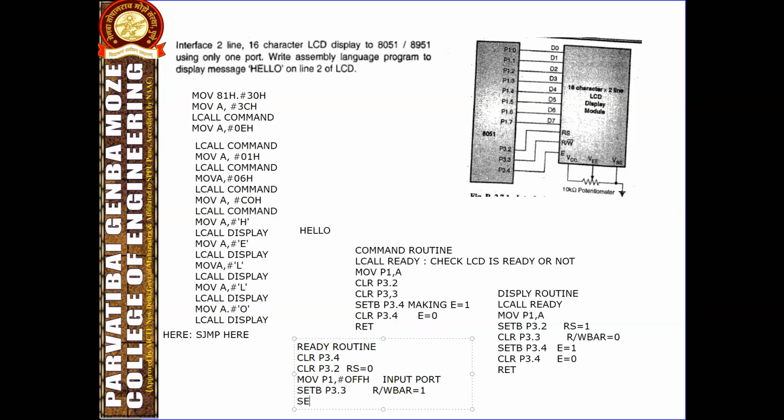Then after that, set bit of P3.4, that makes E equal to 1. Then we have to jump on bit P1.7.